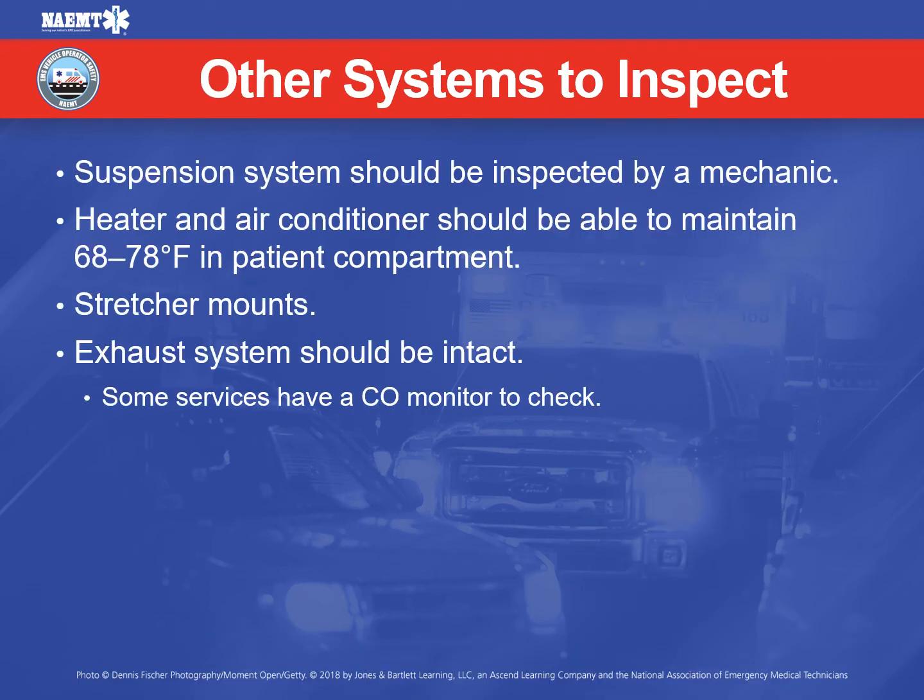Suspension systems should be inspected by a mechanic. The heater and air conditioner should be able to maintain 68 to 78 degrees Fahrenheit in the patient compartment. The stretcher mount should be working properly. The exhaust system should be intact. Some EMS services have a carbon monoxide monitor to check. Along with the exhaust systems, one should check the door seals. A rule of thumb is to close the door on a single piece of paper. If you can pull it through, then the seal isn't airtight and you could be letting fumes into the compartment.